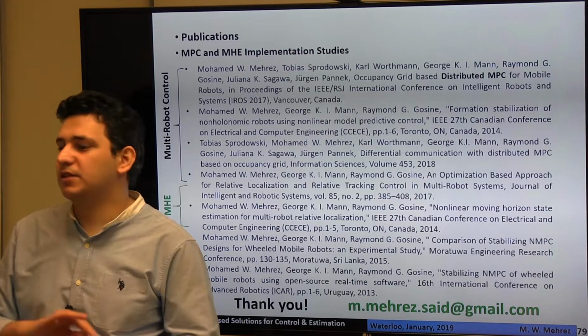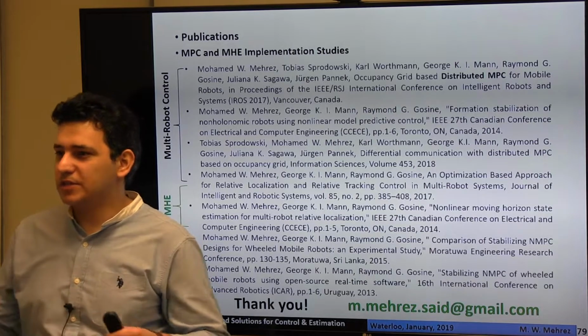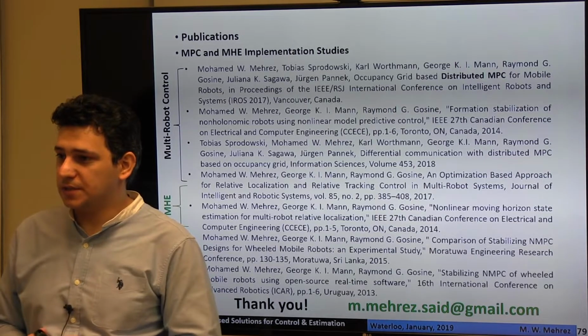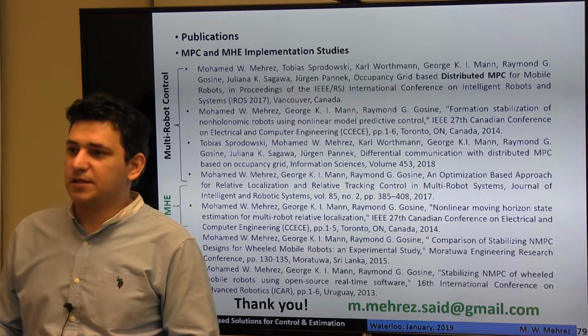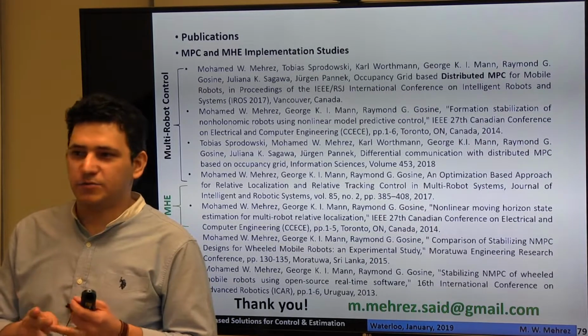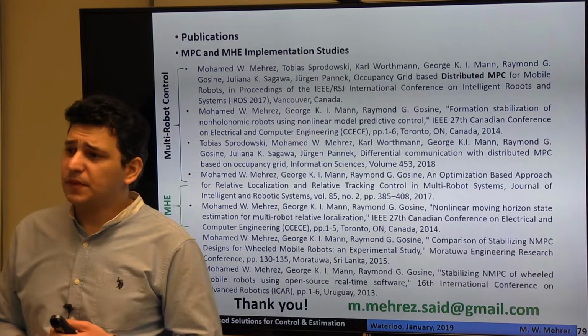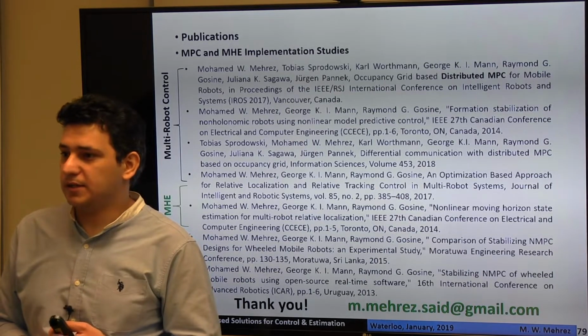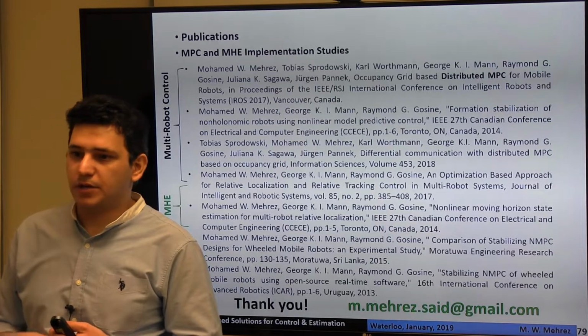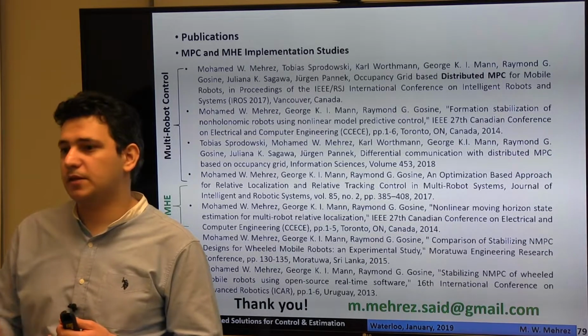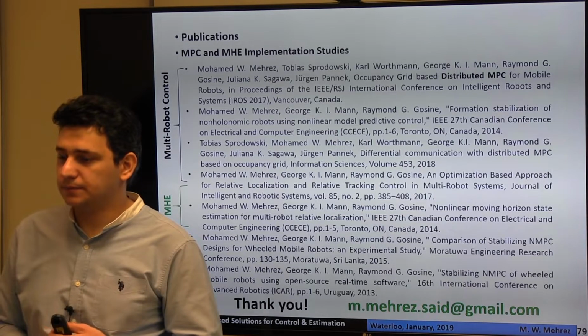If the geometry is really difficult to formulate in MPC, and if you can formulate it, that's nice, because MPC does the planning and gives you the control action, so it does 2 things. But if it's mathematically difficult to formulate, then you can use independent path planning and then do path following using MPC.